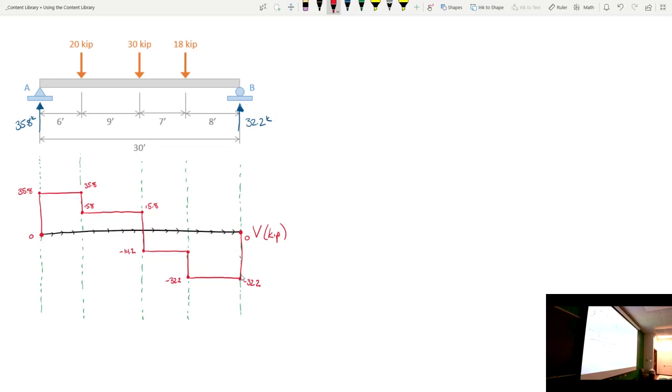There's a lot that this beam tells you that you probably aren't going to appreciate just yet. You will definitely start to understand next semester when you take 216. As an example, if this was a concrete beam, what it would tell me is that I need to place a lot of shear reinforcement near the ends, but not so much near the middle, okay? Because the middle doesn't have as much shear force on the beam as the ends do, which makes sense because that's where the reactions are.